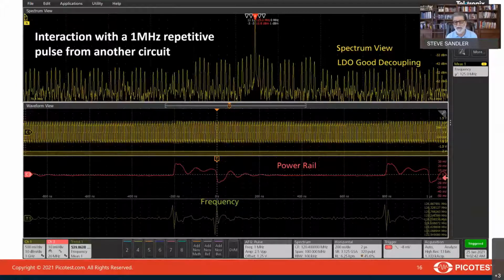Every time we turn on the switch, the output current flows through the input. We put this large current step into the voltage regulator input, and that gets into the power line bus, where it goes through just about everything. And again, if we look at our reference clock, you can see that our 125 megahertz clock falls as low as about 123 megahertz and up about as high as about 127 megahertz. And so again, we've impacted SI just because the power supply switch is turned on.